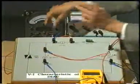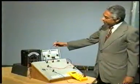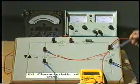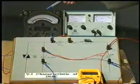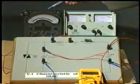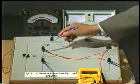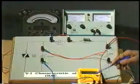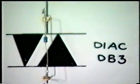So what have I done? I will try to repeat. Number one, first of all, I have connected this power supply across these two terminals, which is a 0 to 35 volt supply. Across these two terminals I have connected this multimeter as ammeter, so it will show the value of current flowing through the device, and across these two terminals I have connected this digital multimeter as voltmeter, so this meter will show the voltage across this DIAC. So this is all about the connection.